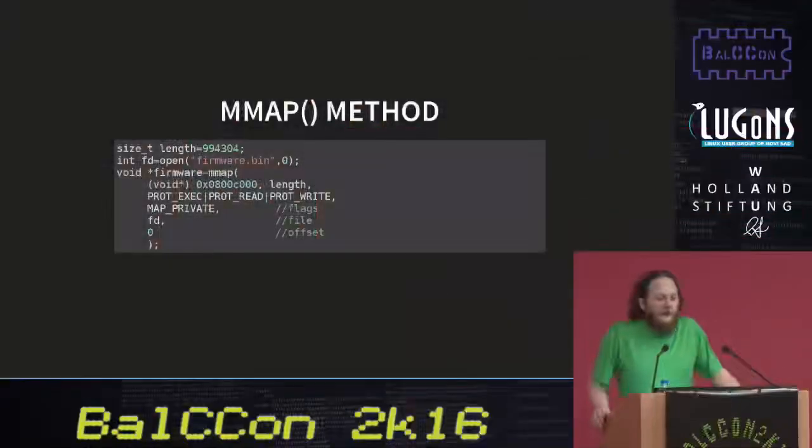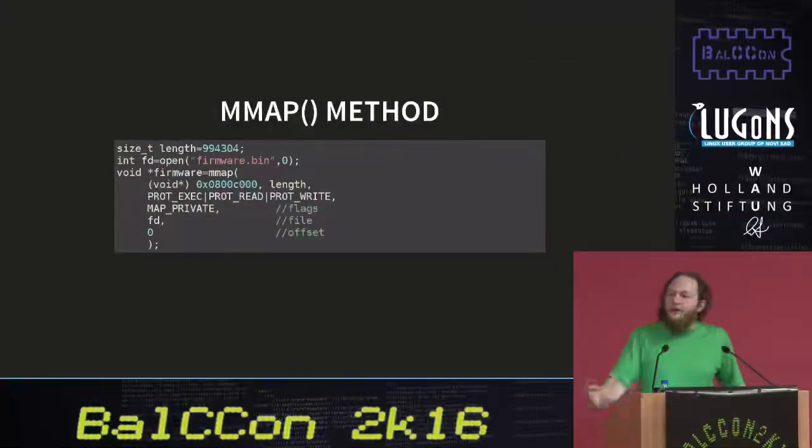So I made this tool, which is called MD380EMU. MD380EMU is the firmware for this radio recompiled to run on Linux. And the code to get this working is very, very small. We're talking 2 pages. The trick for this is I begin with an ARM Linux executable, something that you might run in a Debian shell on an Android phone.